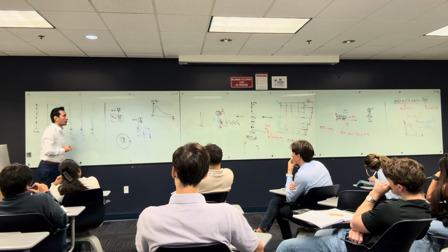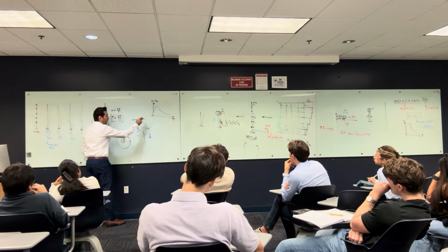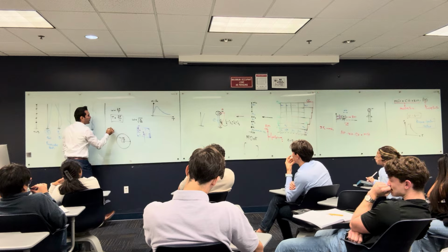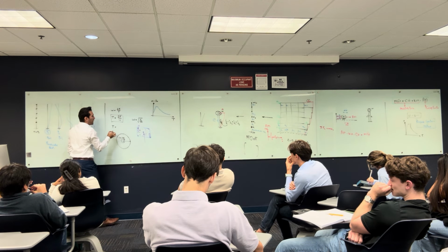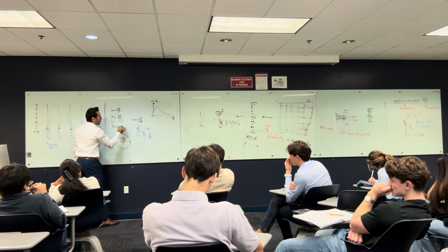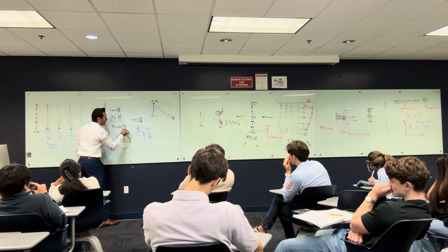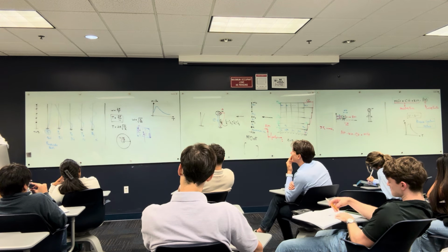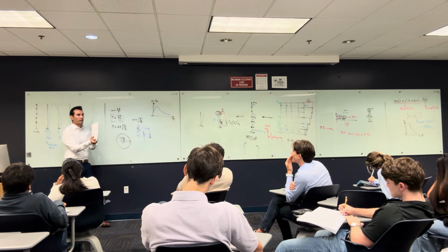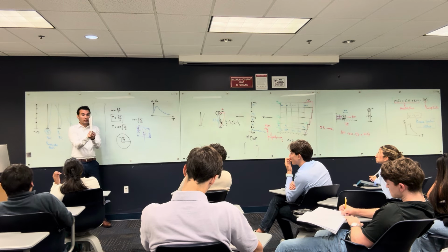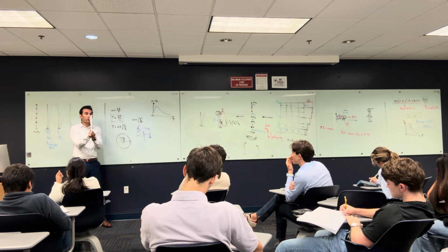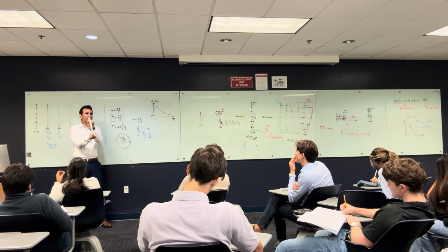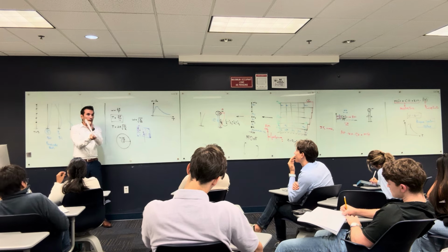The frequency of the structure is the square root of the stiffness over the mass. So if you substitute this here, T is going to be equal to 2 pi multiplied by root m over k. And that actually makes sense. Let's assume that this is my structure. The more the structure is stiff, like if k is really, really big, what is going to happen to your structure? The movement is going to take less time to do the one period.